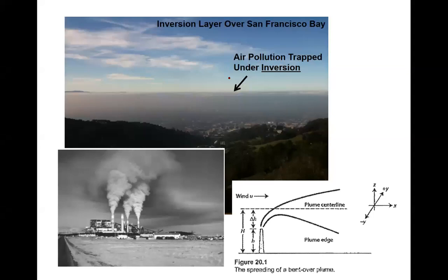So about the atmospheric stability, this is an example of why we would have a stable air that's just at the surface, right? This is because of the cooler temperature on the ground. So it's going to trap these air pollutants. Right? The same for here. You see the stack or the smoke coming out of the stack. They're just trapped within this, I would say, a shallow layer of atmosphere. Right? If people are living closely or nearby, then it's going to be bad for their health. Right? So that's what involved this stack design.